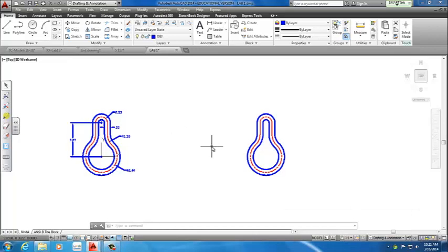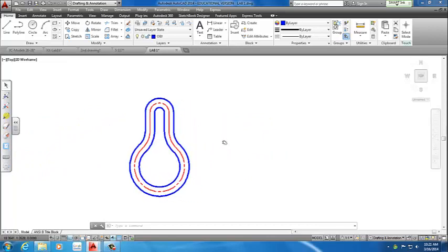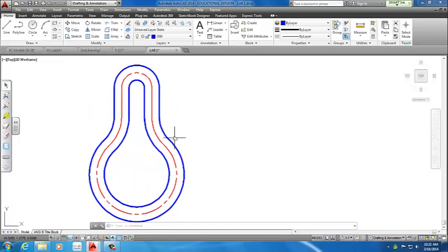Alright, this part will probably be the very advanced part, really hard, so please keep note of this, everybody, even the advanced people. What we want to do is create this segmented line. You can see each part is separate, and we want it to be one single line. To do that, we need to use the polyline edit command, which is called, in short, pedit. So there is no tool for that. We actually have to type it out.